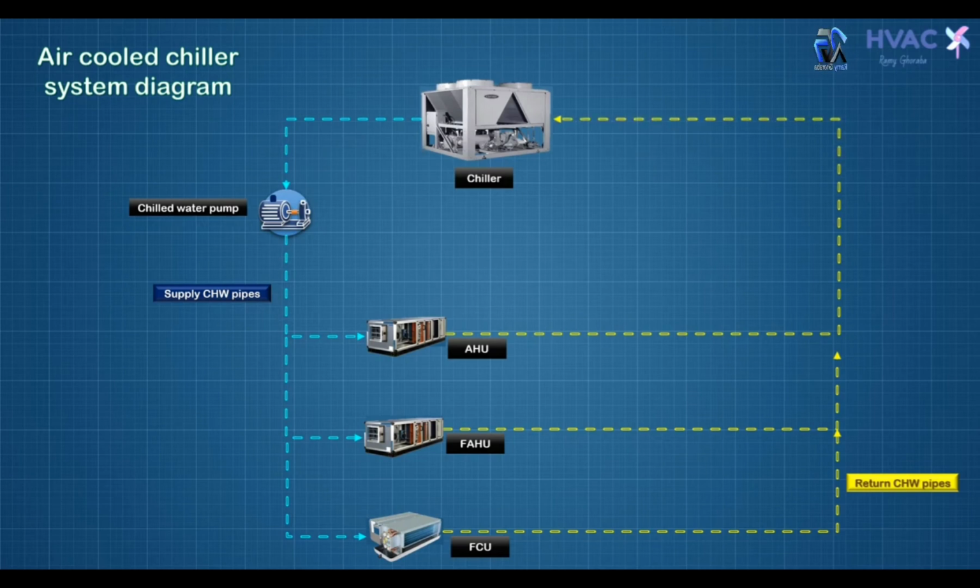Okay, now this is the chiller or the chilled water pipes. How can we get the air cooled in the building? How can I get air conditioning in the building? We have a supply duct coming from the AHUs, and on each branch, as another system, we can install VAV or CAV. VAV means variable air volume, and CAV means constant air volume.